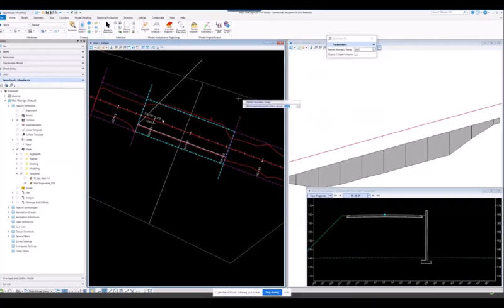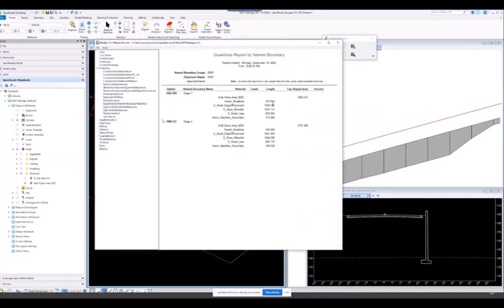What about the points within these name boundaries when I was doing these quantities and this earthwork? All this costing, basically. But you can see in here, 2,900, 2,800. Oh, that's very darn close to 5,700 if I just did the entire model. I mean, we're talking decimals of difference between the two areas just with us clipping that MSE wall mesh into two pieces.